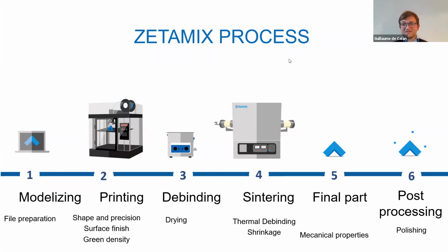Do you observe any shape deviation of ceramic parts compared to the CAD model? Of course, that can happen. Ideally, not. But that can happen. Some simple stuff is sometimes difficult. Having a perfectly flat surface can be a challenge. It depends how it's printed, but it can be a challenge, to give a simple example. So you can have deviation. The idea for us is to try to keep it in a reasonable range where the part is acceptable as it is without any post-machining.